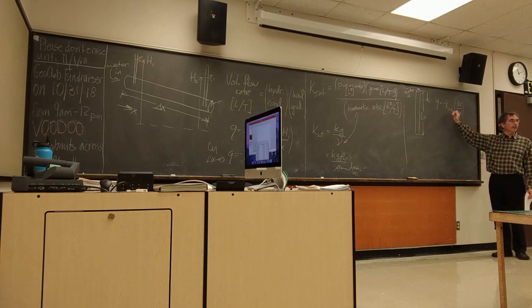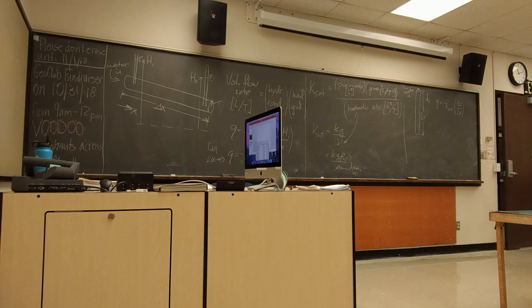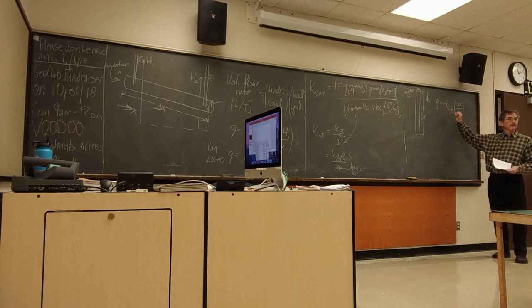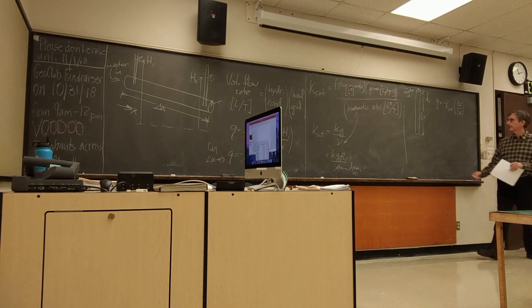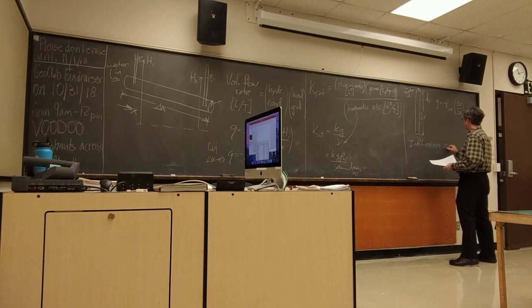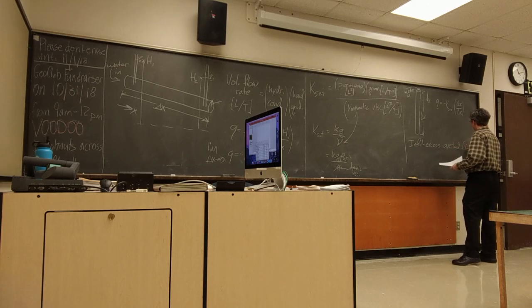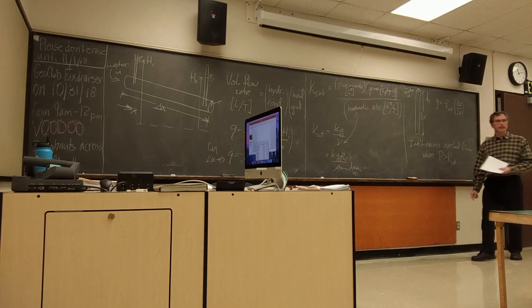So I mentioned last time that our criterion for trying to figure out whether we might have infiltration excess overland flow, which is when precipitation exceeds the possible infiltration rate into the soil, I said, well, if the precipitation rate is greater than the saturated hydraulic conductivity, then we've got infiltration excess overland flow, and this is why. Because our maximum flow rate per cross-sectional area vertically is equal to Ksat. So for infiltration excess overland flow, we get that when the precipitation rate is greater than the saturated hydraulic conductivity.